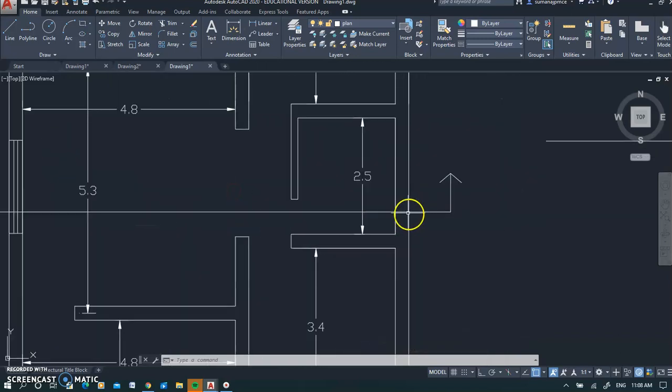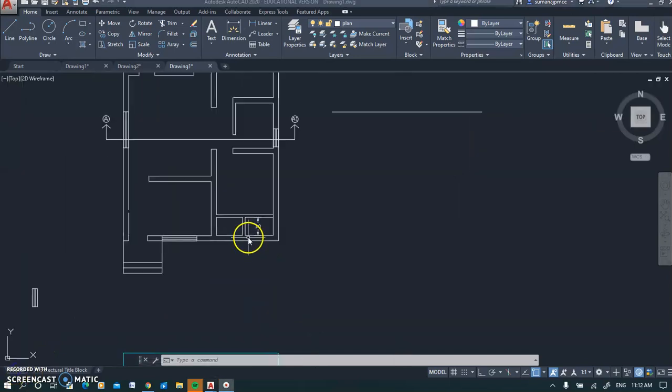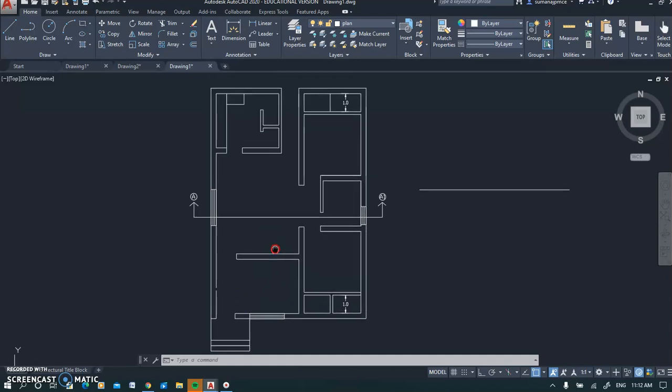Now I could have put a ventilator here as well so that I get more details. So we will now draw the section for this plan, and you can see I have introduced a window, a ventilator, in the bathroom here. So what are the things that get cut here is important. We see the door here is seen in elevation. This is what happens along the section line. And what you see beyond that is the elevation lines. That means we can see this door, we can see this one, this door, we can see one door here.